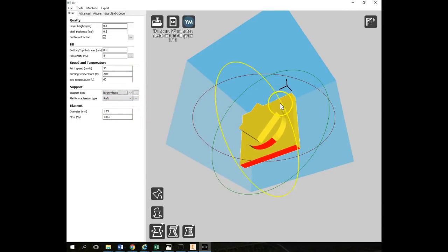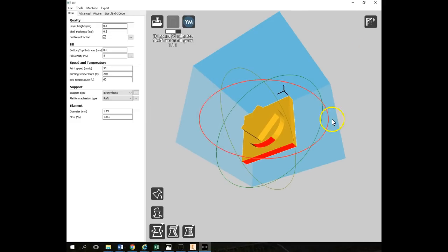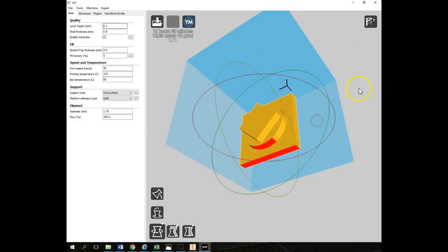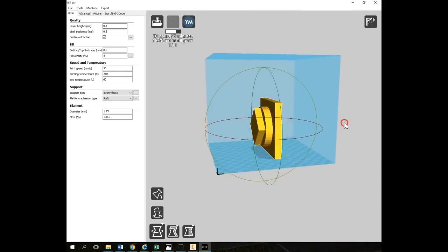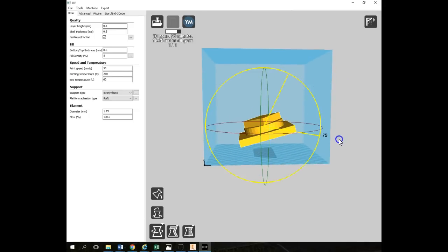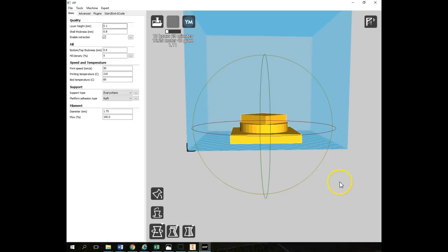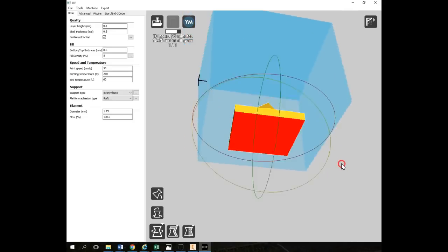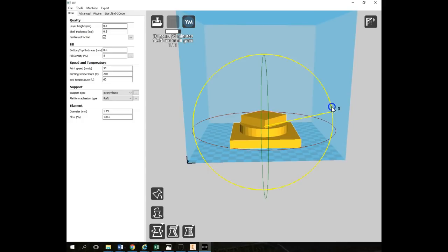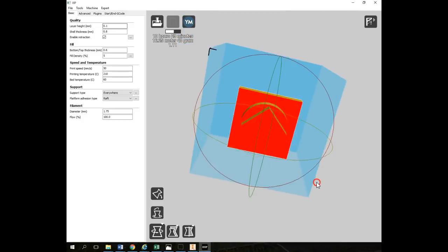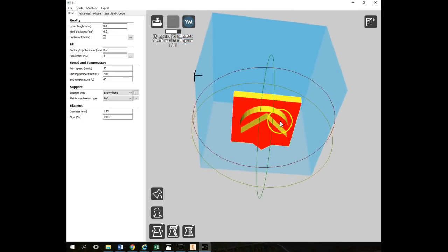I would recommend, and I do strongly recommend this, that you always make sure that you turn your object so that the largest surface area is touching. Okay? In this case, it's like that. If I turned it the other way, could I print it like this? Absolutely. However, it's going to build up fill material to support this structure, the circle, and this larger square. So that means you're going to have to break that material off and smooth it back out.